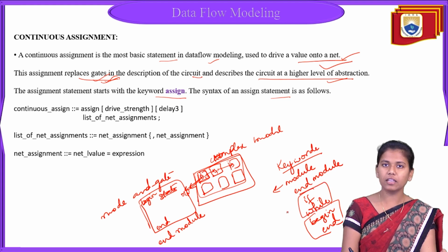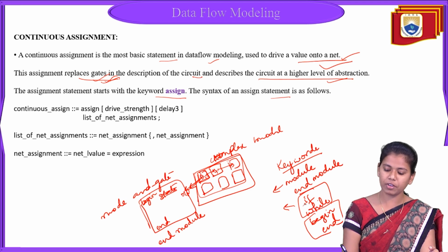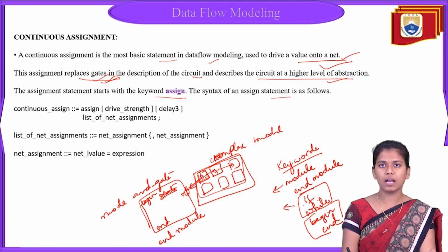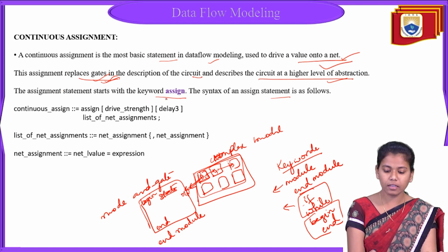As I said, Verilog is a case sensitive language, and it can also be related to the normal C language. So if and while are also used as keywords in different conditions and different areas in Verilog. Coming to the continuous assignment, it starts with the keyword assign, and the syntax follows like this.